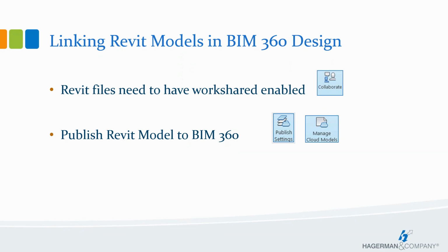You can always republish a model if you've done a save to Central and quite a few changes have been made and you want to let the non-Revit users see what's changed. You can always publish the model again to BIM 360 Docs to update that.